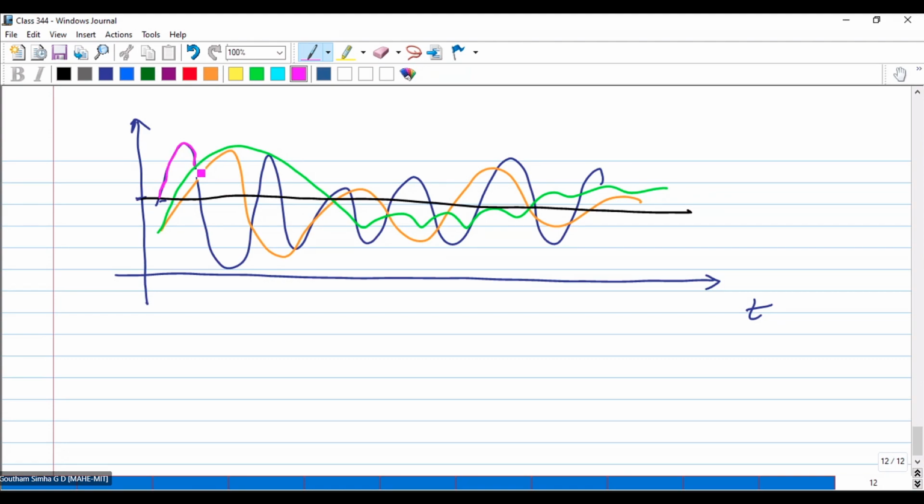Now, instead of switching to green, that is your selection combining, I'll follow this here. Since I follow this one here, I don't have any switching transient here. Now I need to switch back to higher SNR here only.